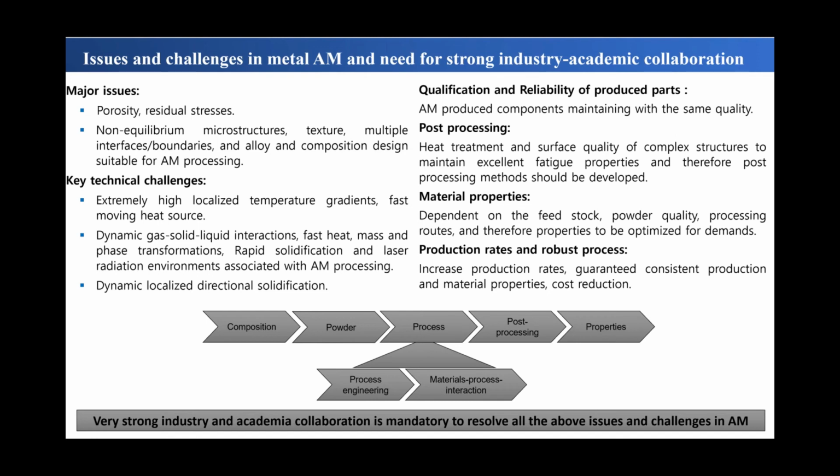Another important point is, as I mentioned in the beginning of my presentation, that these components made by additive manufacturing do not exhibit the same properties as the conventionally manufactured parts. So one needs to evolve a criteria for qualification of these parts. What are the acceptable limits? And then recommendations have to be made for post-processing conditions.